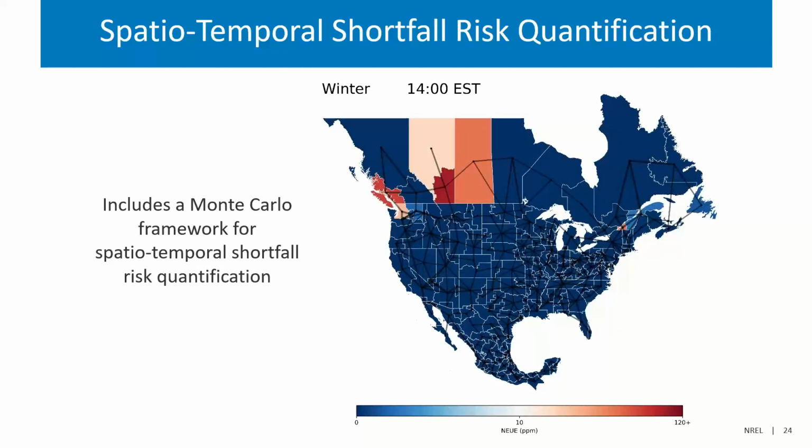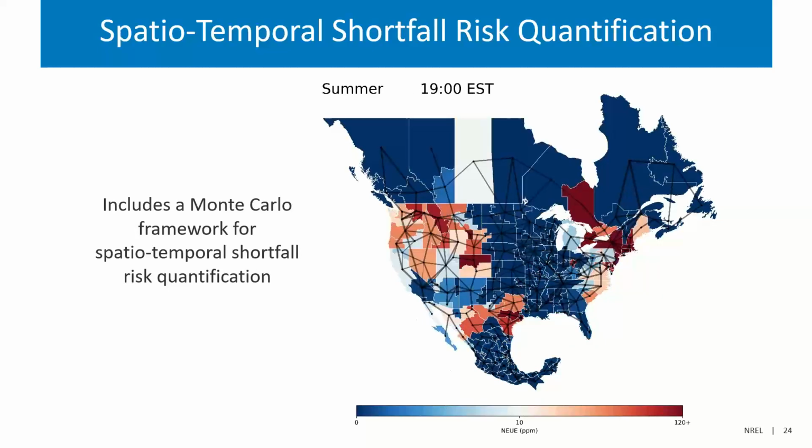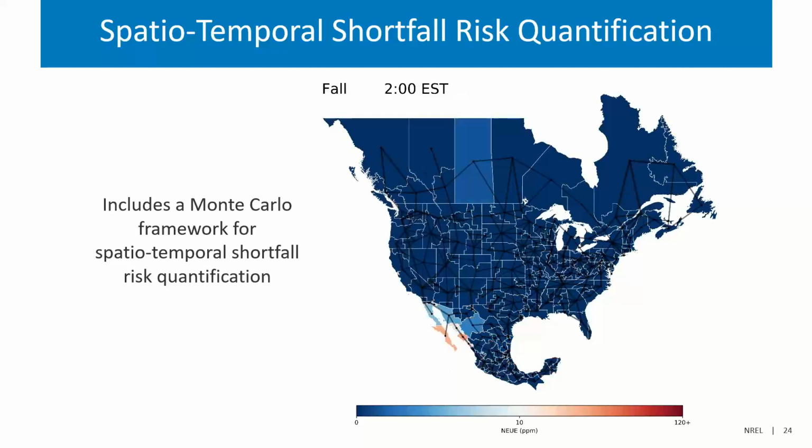Especially as you're increasing renewables. The thing is with capacity factor methods, it doesn't always capture the effect of high penetrations of renewables on the capacity credit. However, with the probabilistic-based method, we see that as you add more wind and solar onto your system, you actually get a drop in the capacity credit. That's something you might not see with the approximation-based methods. So for sure, system operators are looking into probabilistic methods, especially as wind and solar are increasing on the system.